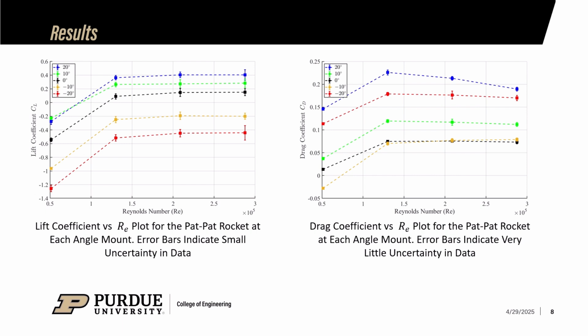For lift coefficient, similar to the force data, the negative angles of attack have negative lift coefficients as they cause the ship to go down, and the 0 and above angles of attack, since they lift the rocket ship up, have positive lift coefficients, which increase roughly linearly with the angle of attack.